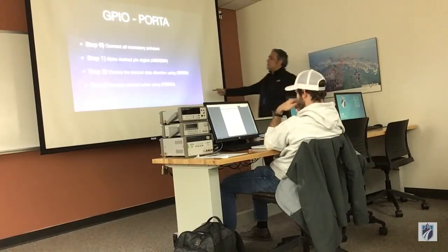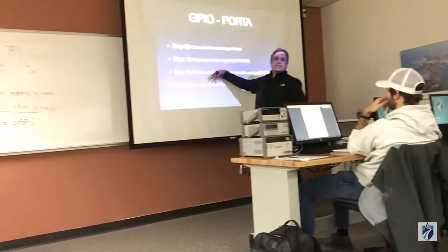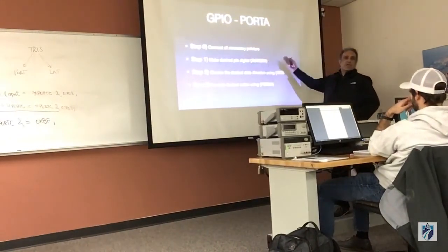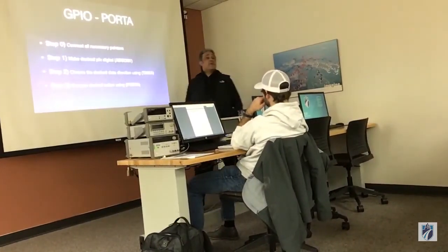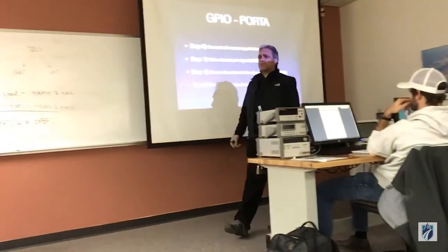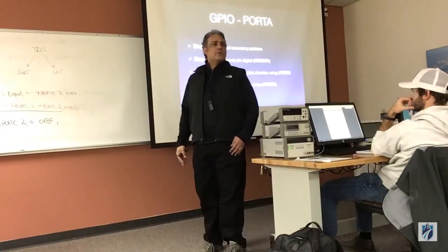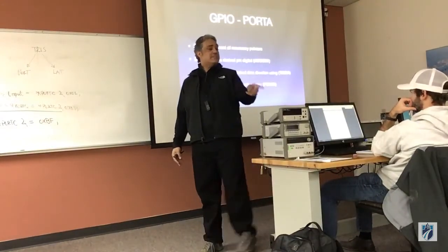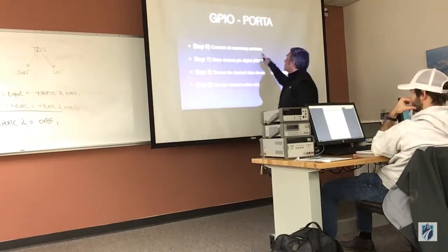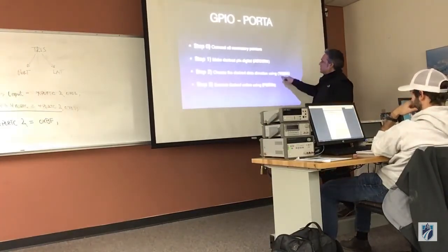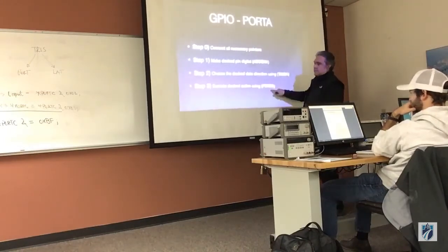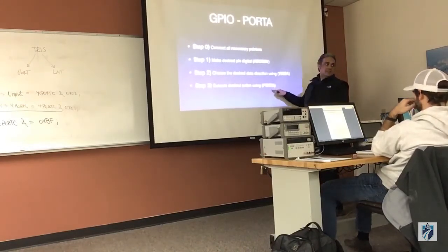So this is nothing more than a reminder, so you can actually take something like this and bring it to the test. You can use it as your reminder. Somebody says, read an input from port A, or somebody says there is a switch connected to port A0. Oh, there's a switch connected to port A0. That means there's an input, so I need to connect all the necessary pointers, make the pin a digital pin, set up the tri-state as an input, read. Right? It's kind of like a reminder.